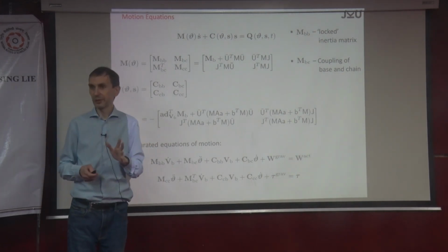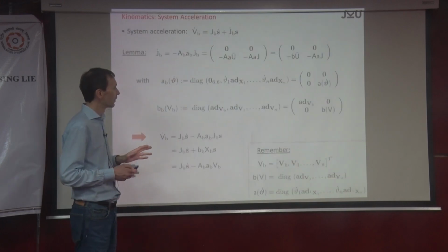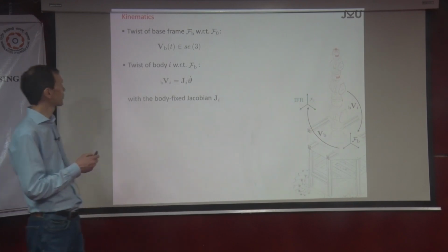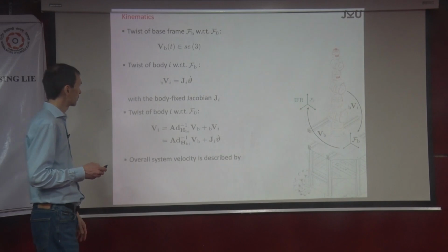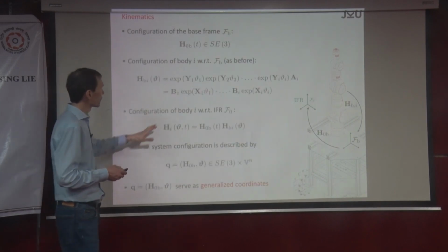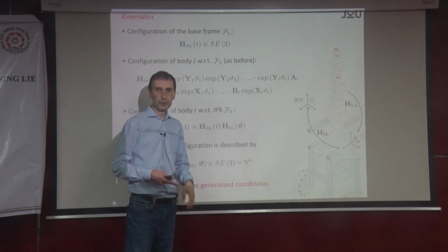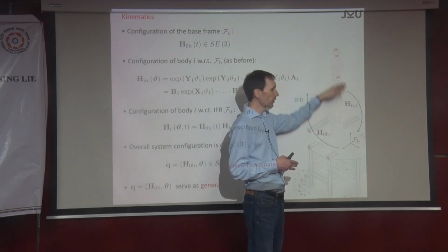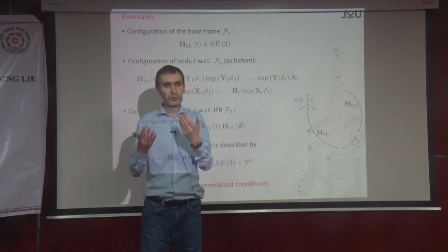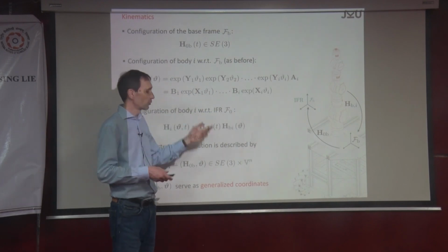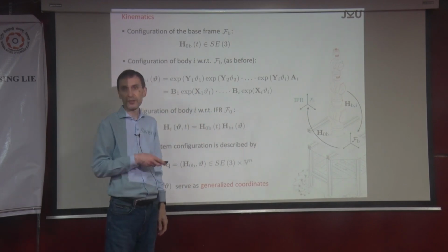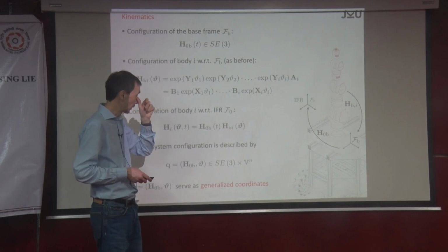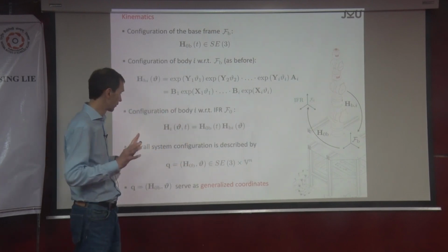So the question is, what do you mean by measuring? Maybe just to repeat again, what goes into the equation? Maybe start from the kinematics. What do you have to do? You have to, first of all, find the screw coordinates of the joints. This is what we said is easy to do, because you just need to measure the vectors of the joint axes, and that's it. And this goes in x, respectively y, depending on what you want to do. So that's the kinematics, really easily done.